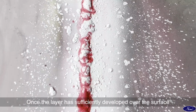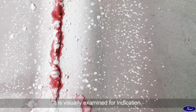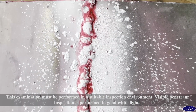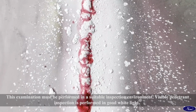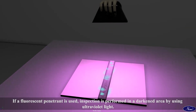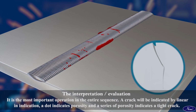Inspection. Once the layer has sufficiently developed over the surface, it is visually examined for indication of the penetrant bleeding back from the surface openings. This examination must be performed in a suitable inspection environment. Visible penetrant inspection is performed in good white light. If a fluorescent penetrant is used, inspection is performed in a darkened area by using ultraviolet light.